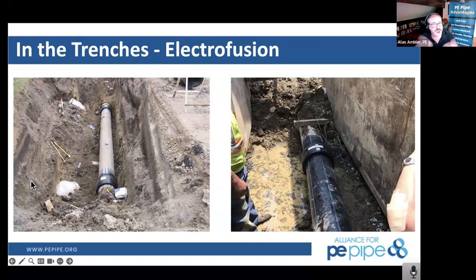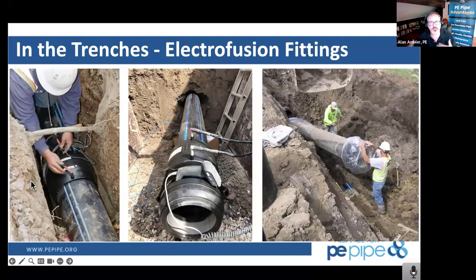Then they'll line up the pipe ends at the appropriate location and bring that coupler back to be able to perform that. These electrofusion fittings need a little bit more operator involvement in preparation of the pipe surfaces to be able to get back down to that virgin resin material. All they're doing here is connecting to the fitting with the electrofusion processor. They scan a barcode, and then everyone's fittings across the entire industry are recognizable from that barcode. That processor will fuse that electrofusion fitting for the right amount of time needed to get you moving that molten material across.